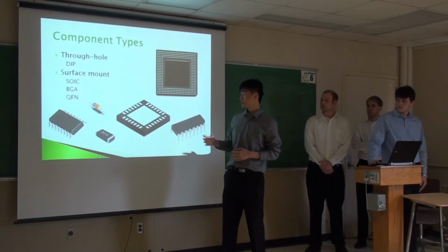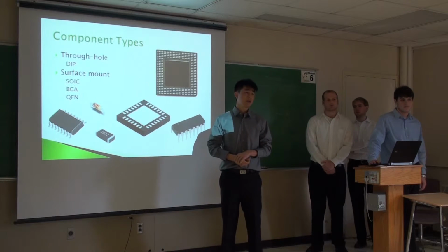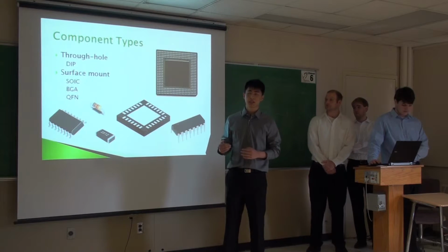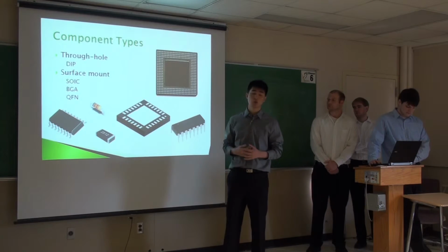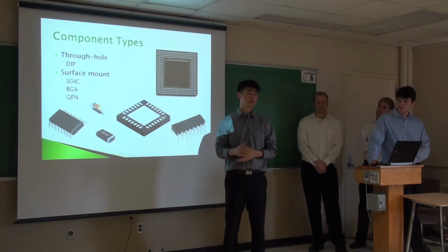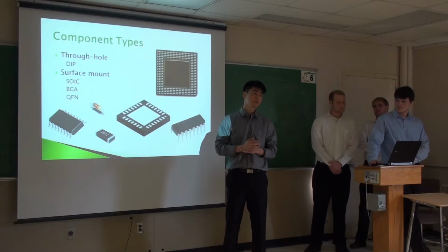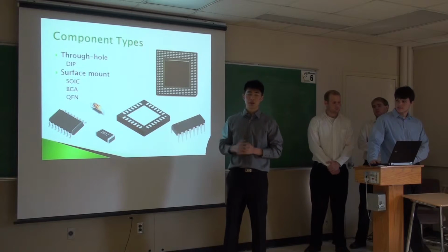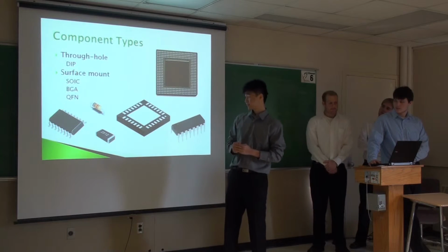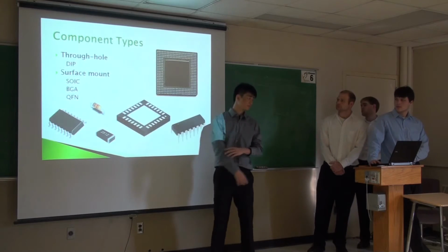Another reduced lead chip is QFN, which stands for Quad Flat No Lead. It's a pad with a copper lead frame and a thermal pad. The advantage is low weight, thin profile, near chip scale, and most importantly, the perimeter pads are on the PCB traces. And here are some through-hole and surface mount resistors.